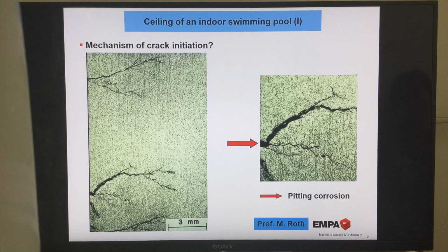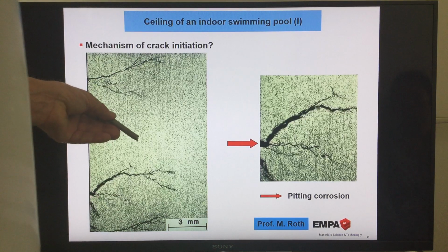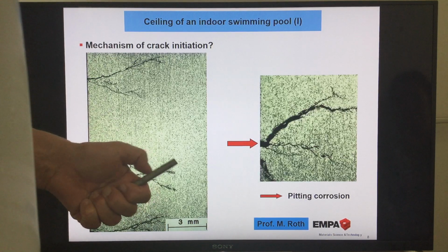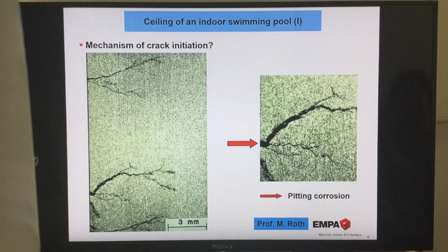However, as I told you, when we have these mechanisms of the slip bands with the dislocations, and the dislocations pile up at the surface, they can destroy this thin layer, because this thin layer is quite brittle. And when this thin layer is destroyed, normally when I scratch here, after, let me say, 1 or 2 hours, it will be self-healing, because we have all the time oxygen available from the outside.